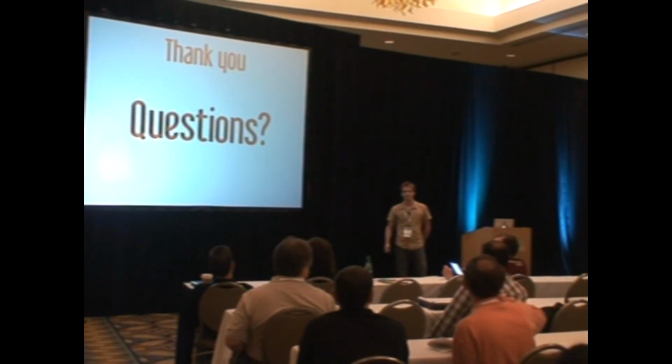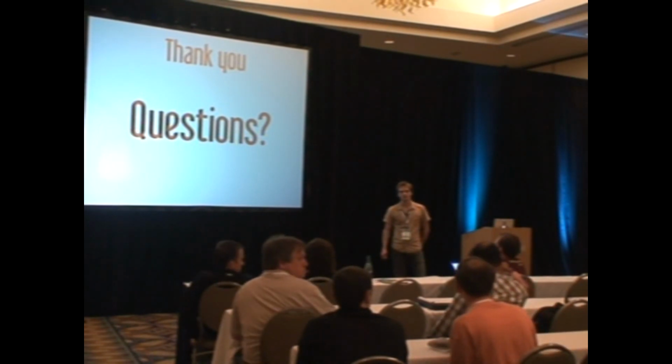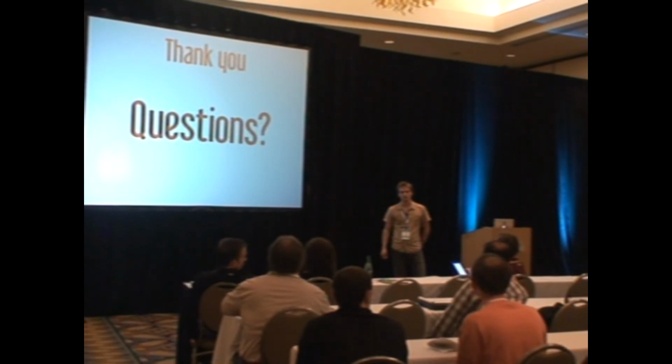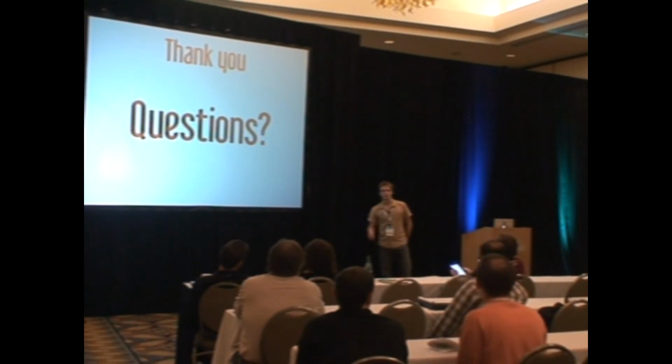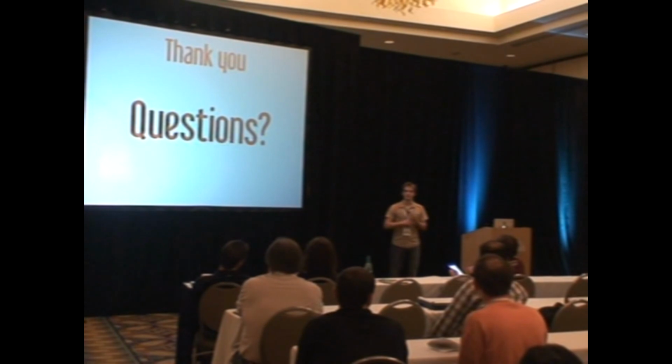Yes? ETM traces the program counter, as I understand. Is it possible to also trace writes to particular data areas? I want to see when I'm modifying. Yes, with ETM you can. The question is, is it possible to trace something else than instructions? You can trace data, so you can trace reads and writes also. This is an interesting feature.